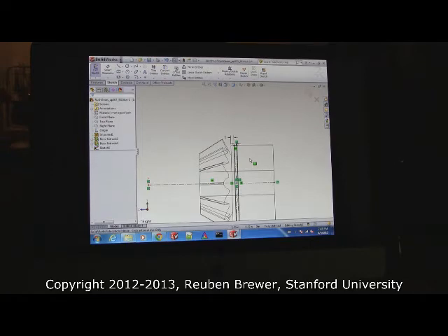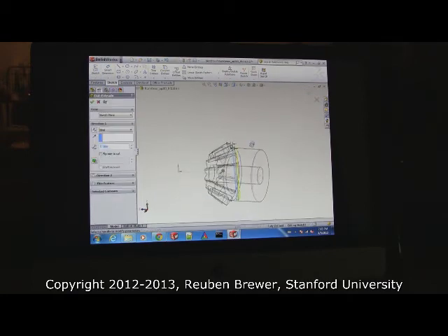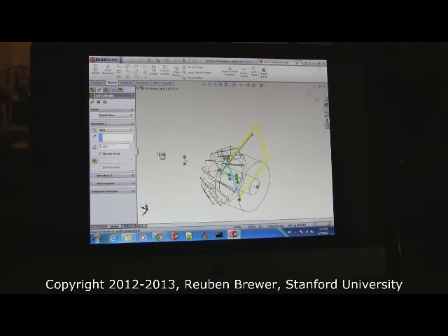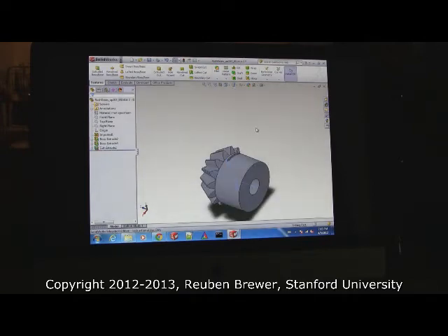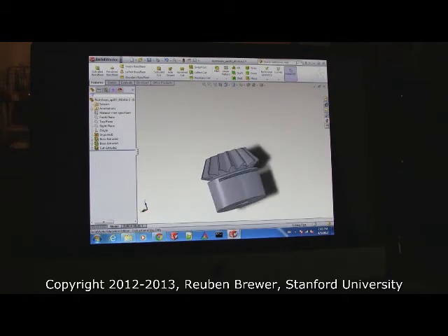Okay, is everybody with me? Now exit the sketch with the little pencil thingy. And if you did it right, you'll see sort of a yellowy thing. This is what we want. Set it to 1 inch. And hit the green check mark. How do we get to the yellowy thing? Exit the sketch through the purple pencil. 1 inch. Basically, we want to cut all the way through that body. Just half of it. Okay, now turn back on the shaded modes. This is what our part looks like now. Look at that. That's sweet. Does everyone's screen look like mine?